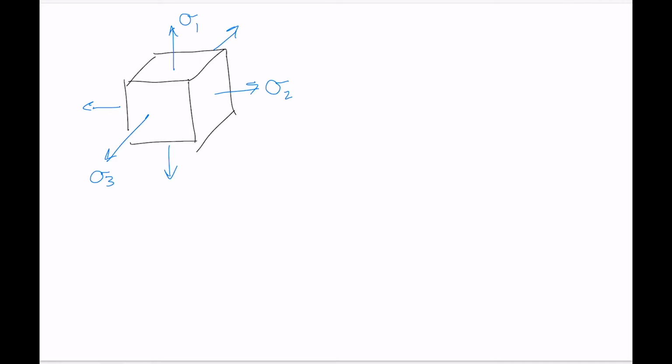Okay, so what's the relationship between energy and stress and strain? Well, the relationship's really straightforward here. So if we look at just a stress-strain diagram, normal stress, normal strain, we know what the stress-strain diagram for a ductile material looks like, something like that. If you take the area under the stress-strain diagram up to any point, let's just say it's that point there, then you're taking the integral of stress with respect to strain.